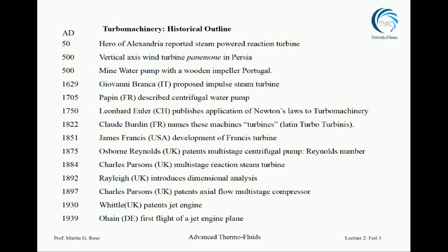Rayleigh, who I think was a British physicist, I don't know much detail about him, came up with the concept of dimensional analysis, which is the absolute cornerstone of fluid mechanics and turbomachinery. And this lecture will describe to you the basic process of doing dimensional analysis. Reynolds number is one of the results of dimensional analysis, and there are many other such numbers. They're all, as the name suggests, dimensionless, and that is the key to their value.